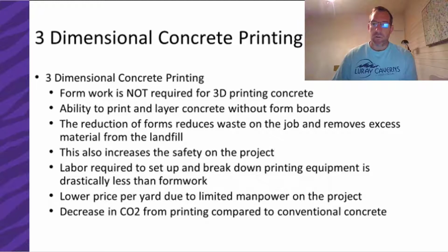In my backyard, actually just last week, we met with a vendor who is taking recycled concrete. They're taking concrete from washout pits. They're crushing it. They're turning that into number 3s, which we're using for construction entrances. They're turning it into aggregate that we're able to reuse and prep slabs and do other things. They're able to even make crush and run with this product. So the concrete served its purpose for the building that we wanted to build, but then it also serves its purpose to give us something back down the road, which is a huge benefit to our industry.